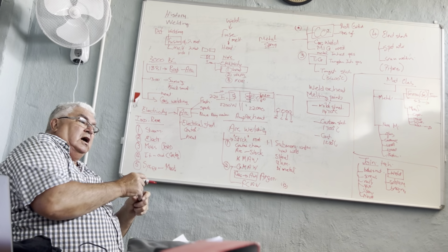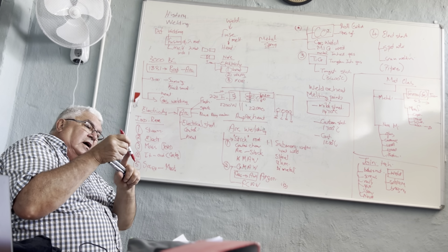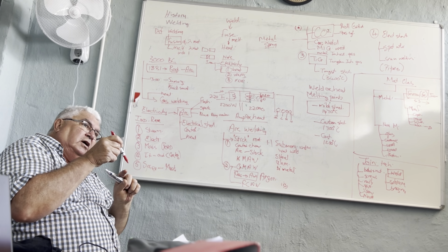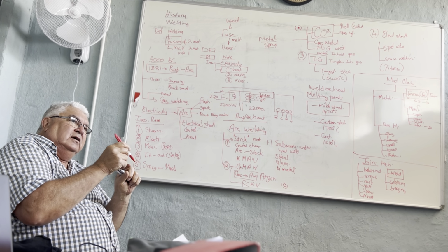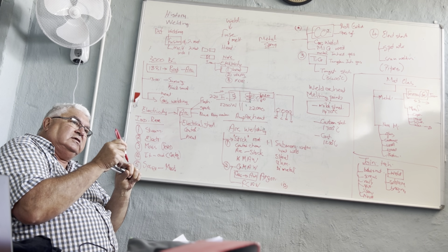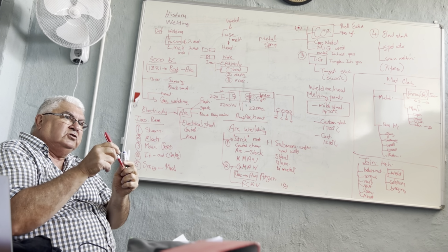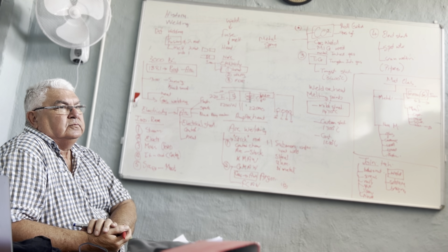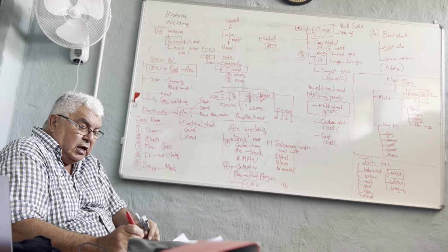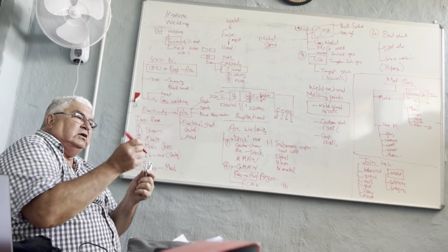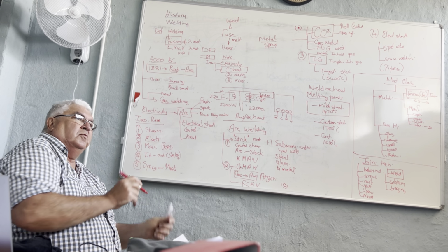Now, how does TIG work? I've got a tungsten rod, tungsten melting at 3,400 degrees. I create an electrical short, a little short there, like a car spark plug. And it doesn't burn away. So it creates that spark and that very focused heat source. The tungsten is there to get the electrical short, and you sustain it. Once you've melted your material, you can see the puddle, and you just add filler rod to your puddle.